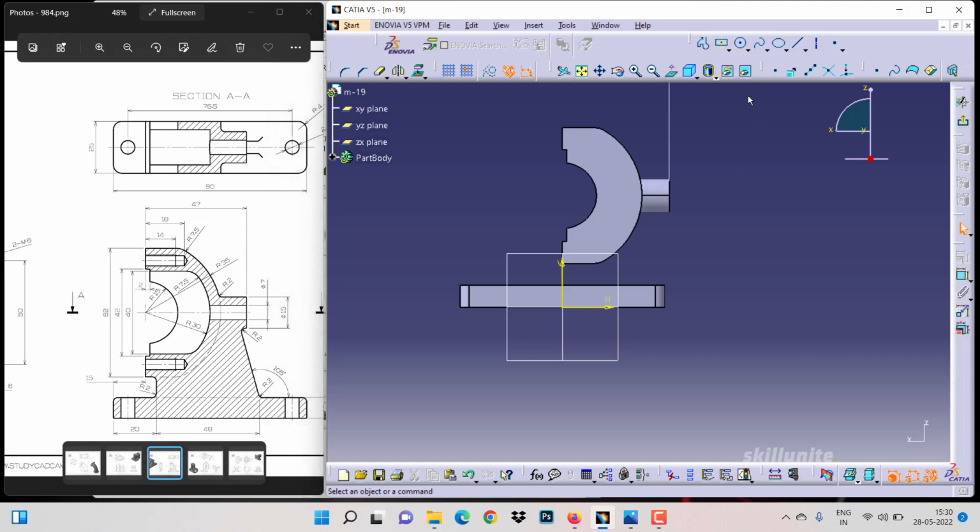So what we have to do, we have to try it with normal extrusion, that is pad optional. For that reason, let me just use this projection tool over here. Let me project this one, let me project this thing also. This one also you can project, and the filleted edge. Then we need to close it over here like a straight line.